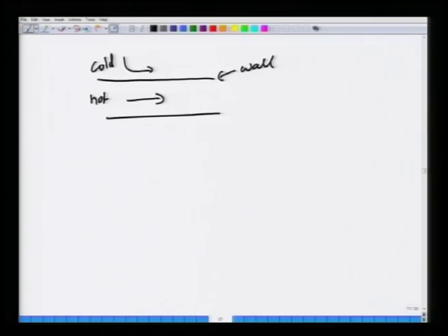Okay. Now, how heat transfer happens between these two phases depends on the detailed nature of flow. Okay. For example, if the hot fluid is flowing like this, in only one direction. So, fluid is flowing in this direction, and there is a temperature difference between this fluid, this T inside is different from T outside. This provides a driving force for heat transfer in the direction perpendicular to the flow, but since there is no fluid flow in this direction, heat transfer can happen only by conduction.